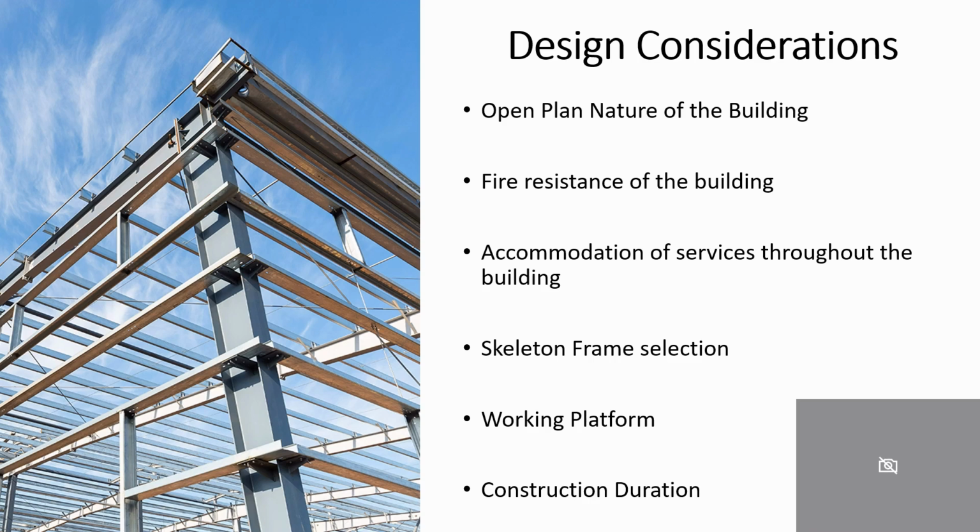And due to the skeleton steel frame, the concrete slab construction allows for effective collaboration, and the steel frame combining with the hollow core concrete slabs allows for a cost saving, as the tonnage of steel beam required can be reduced by up to 40% in comparison to metal decking. The concrete flooring finish also offers a working platform while the construction is being carried out, therefore other trades can carry out work safely and effectively.